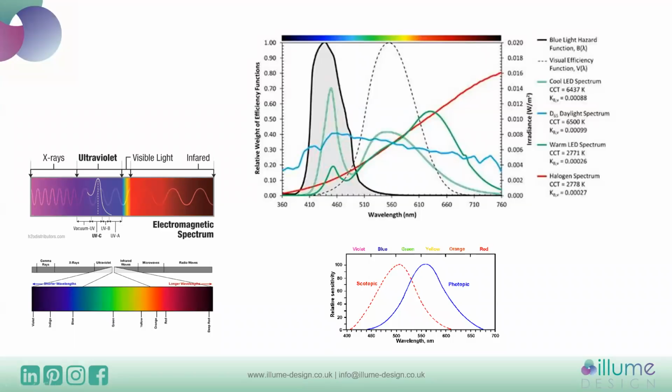The other reason is that efficiency in LED is much higher in the blue spectrum, because essentially an LED is a blue light. So in order to make it white or warmer, you have to add phosphors to the LED, which decreases its efficiency. So when there was a very big energy drive initially with LED, it was beneficial for lights to be cool white, and we saw some street lighting that went in that was quite blue in its tinge, and it was because it was so efficient. And from our point of view, we would view it to be brighter.